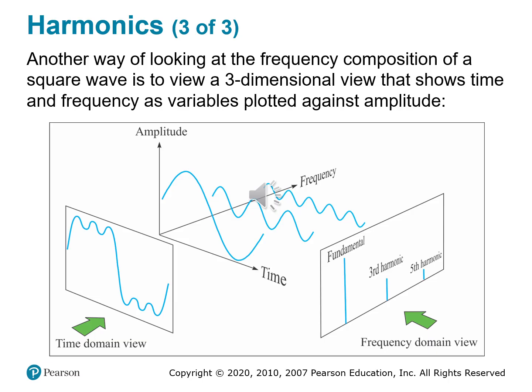And so why is that important? Because again, in electrical engineering or electronic engineering, time domain helps you diagnose signal shape, delays, and distortions. Frequency domain lets you analyze filtering, bandwidth, interference, and spectrum use. So together they provide a complete picture of signal behavior.